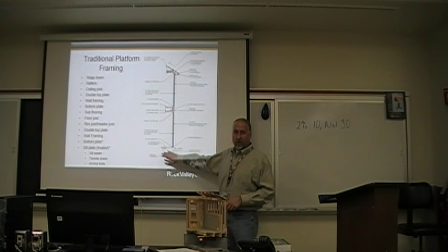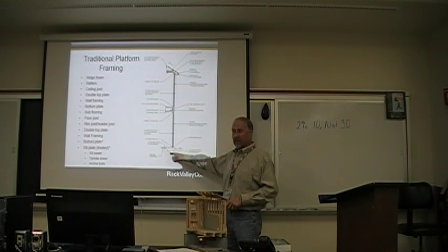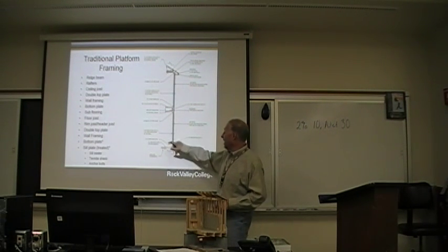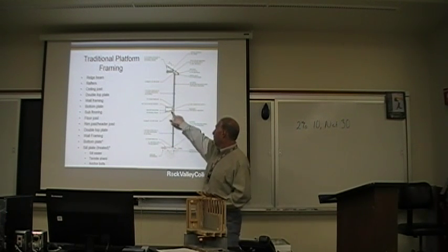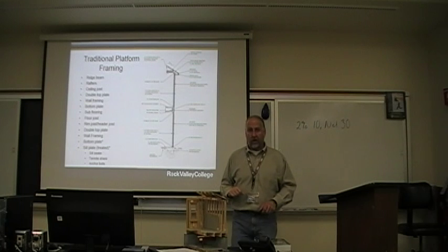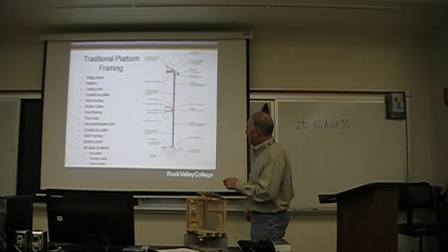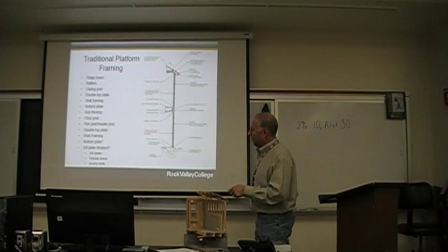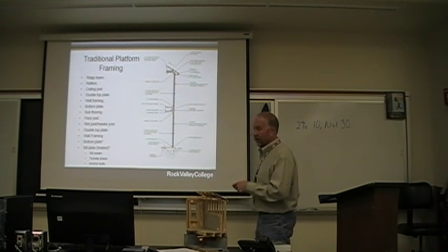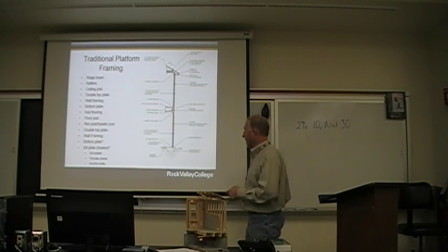Okay, coming back here, that's these sections in here. Now, we're showing a slab on grade situation with a grade beam. We'll talk more about that when we talk foundations. But in here we have our second floor, and we're using a rim joist along with traditional floor joists that go across into here, and those are our main floor structures.